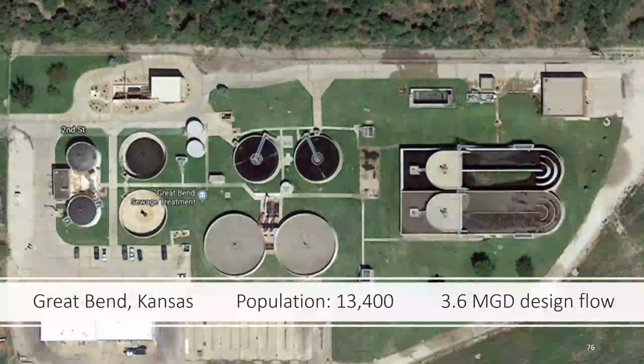I think my recommendation, Chancey, would be to target your ORPs. Try to target the ORP during the air on cycle to reach positive 150, maybe keep it there for 15 to 30 minutes. And then that would determine your air on cycle. For your air off cycle, I would target a minus 100. And again, I'd keep it for 15 to 30 minutes at minus 100 once you reached it, and then I'd go back to air on, figure out how long those cycles are. Or if you got real fancy, you could run it off of inline ammonia and nitrate probes that actually measure when your ammonia removal's good, stop aerating. When your nitrate removal is good, start aerating.